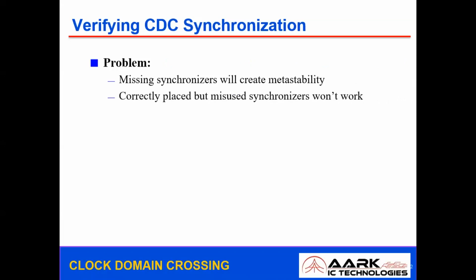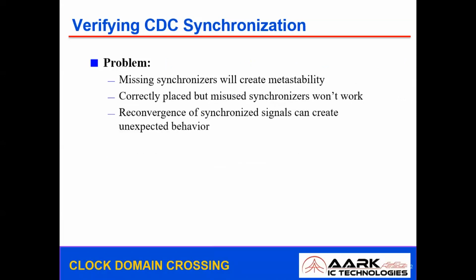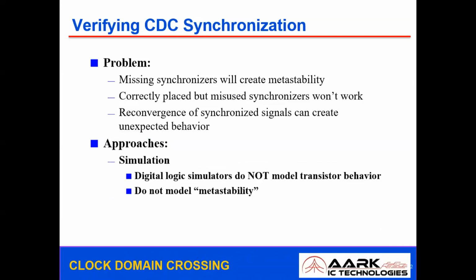Correctly placed but misused synchronizers don't work. Reconvergence of synchronized signals can create unexpected behavior, so this needs to be addressed. Approaches: simulation is one thing. Digital logic simulators do not model transistor behavior, so they do not model metastability. So that is not possible.